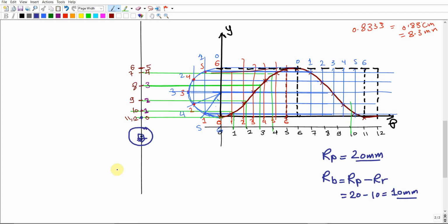Then your objective is just to break it down. You're gonna break this circle into 12 sectors. If you divide 360 degrees of rotation by 12, this is gonna give us 30 degrees. So your objective is just to measure, starting from the vertical axis, 30 degrees to the right and draw a line, then another 30 degrees and draw a line, another 30 degrees and draw a line, and so on. So you're gonna end up with the 12 sectors. And this is what we're gonna do. So your objective is just to break this circle down into 12 sectors in this way.